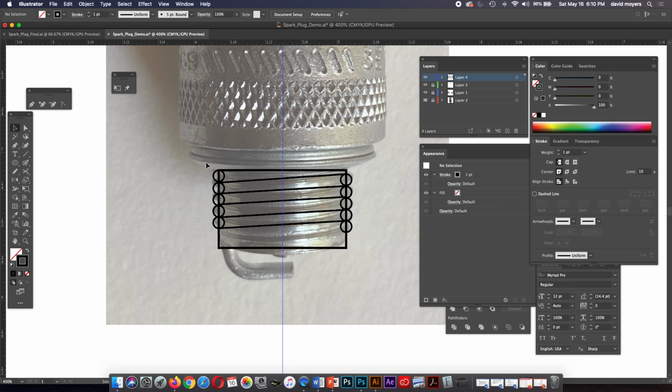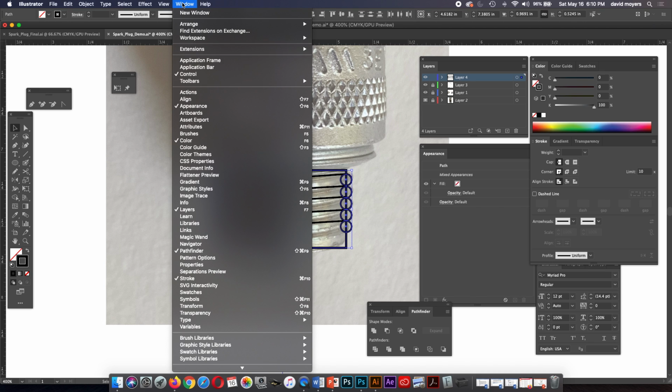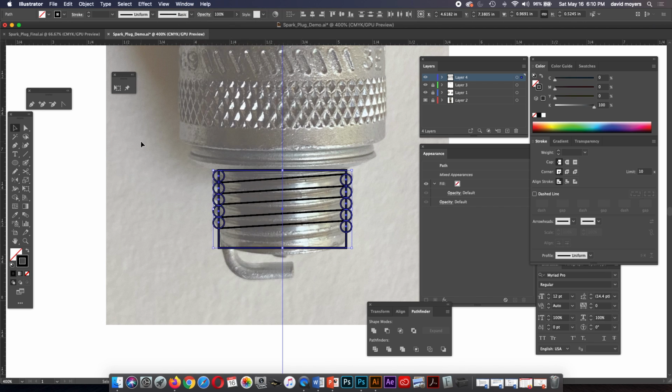Now, what I'm going to do is combine these shapes. So I'm going to select all my circles. I'm not going to group them. I'm going to combine them with the rectangle. So I'm going to take my rectangle shape, and then I've got my Pathfinder tools here. If you don't know where those are, if you haven't used them, they're under Window, and you go and look for Pathfinder. The first button here is called Unite. So if I unite that, I get this.